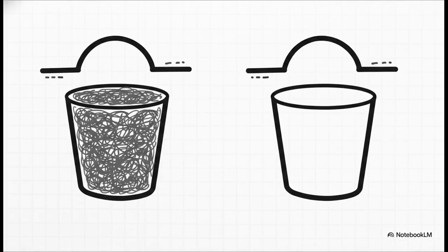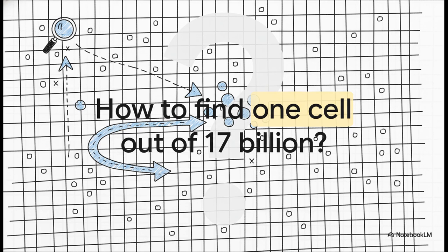Let's look at the working principle. In simple words, a charged capacitor at 1 volt gives us a binary 1. An empty capacitor at 0 volts gives a binary 0. The word line connects to the transistor gate to turn it on, and the bit line acts as the data bus. Students usually confuse these two wires, so remember, word line is for control, bit line is the pathway for data.